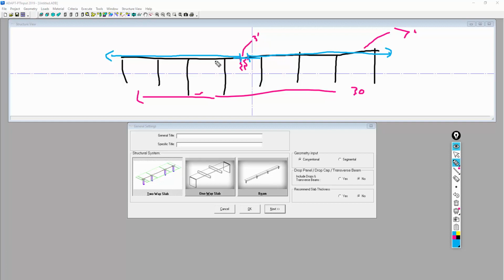You could build multiple models that might be required to capture different stages. For example, if the shoring is not here, and this is a cantilever, let's say left, and a cantilever right, we might have to build 3 models. We might have to look at model 1 on this left side, model 2 on this side. Those are kind of completed in different stages, and then model 3 is the full system again. So we're really looking at model 3, assuming that this is shored. And what we're going to focus on is really how to set the tendons up here.